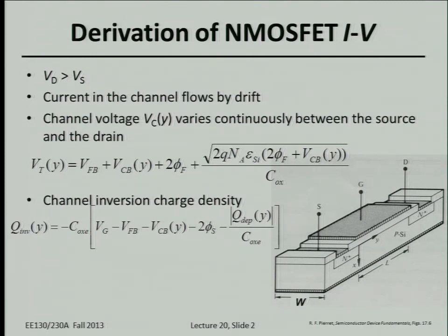As illustrated here, MOSFETs are three or actually more, four terminal devices. Based on our qualitative understanding of the current conduction in the MOSFET, once we apply a high enough gate bias, let's say, when the gate bias is over the threshold voltage, we're going to generate inversion charge in the channel. Because in that case, the depletion charge concentration in the channel will be fixed, right? So basically, the added gate voltage will try to boost inversion charge in the channel, so that the gate can modulate the resistance of the MOSFET transistors.